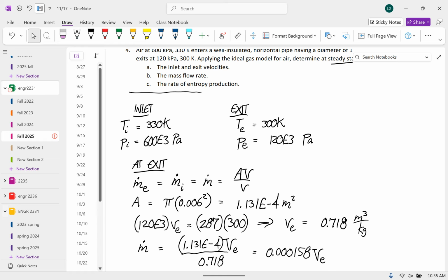And we did one where the temperature range was 800 degrees Celsius, and we still got 10% error or something, so 30 degrees Celsius, you can feel pretty good about that. Yeah. So as far as using CV and CP, it's all about temperature. You don't care about any of the other things. It only varies with temperature for an ideal gas.